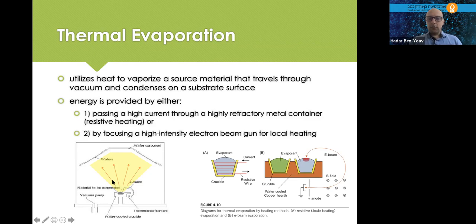And then the vapor phase of the metal, such as vapors of gold, is transferred towards the wafer itself. So we have here two wafers, and the material gradually deposits physically on the surface of the wafer. This is the way we evaporate metals such as gold and make a very thin metal coating on the surface of our substrate, for example, for electrode fabrication.